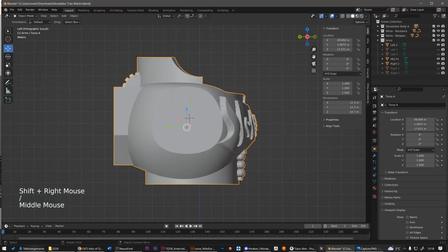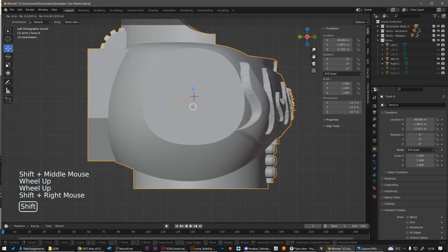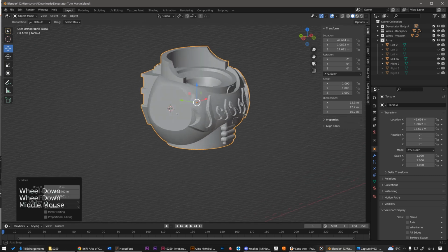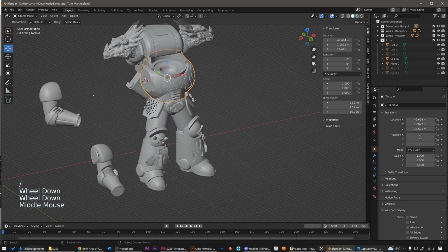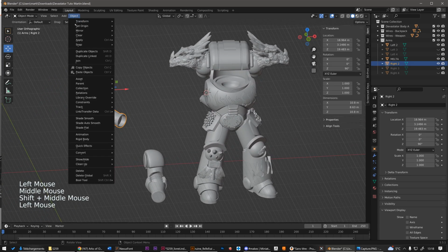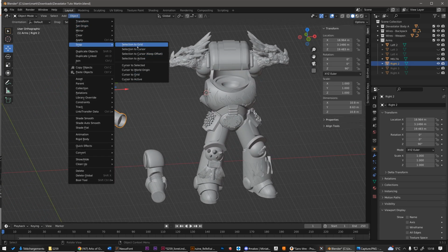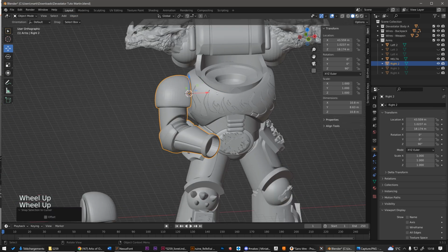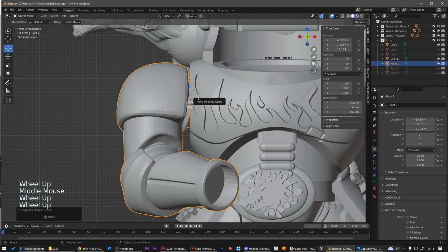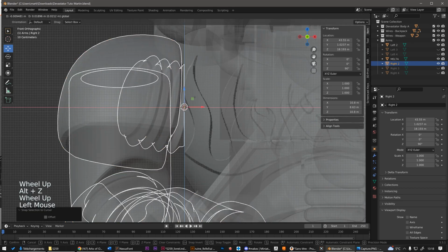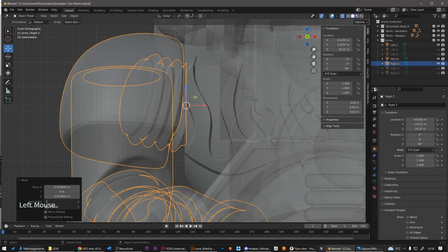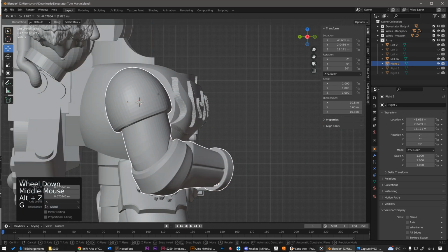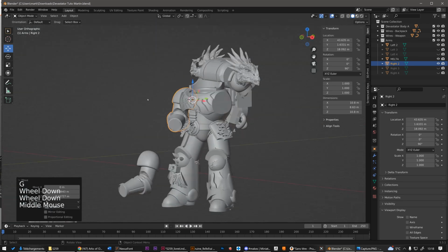So with a side view, we will position the 3D cursor where we want to place the arm. On the same joint where we placed the arm's origin, so around there. And then, we simply select the arm, and in the Object menu, Snap, we can now position the selected object on the 3D cursor. And here it is. With a few clicks, the object is almost perfectly positioned. Now we can do small adjustments, like making the arm intersect well into the body or better centering the shoulder.